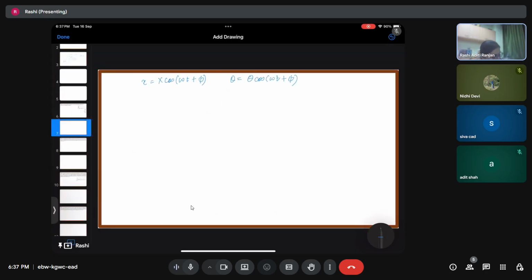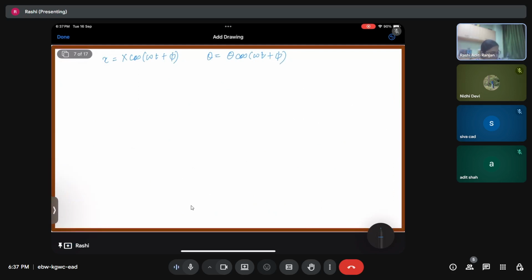We get the equation in the matrix form as [-4ml²ω² + 2kl², kl; kl, -mω² + 2k] into Θ and X is equal to 0, 0.